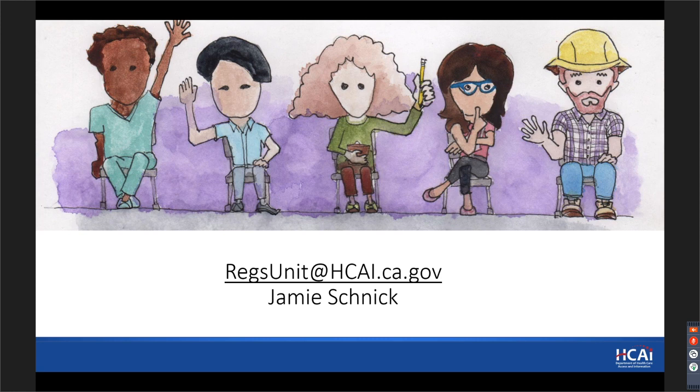So to answer the question, is this required over transformers? The answer is no. To answer the question about whether I am allowed to have sprinkler piping that's 6 feet 6 inches above the equipment, that is code permissible. I would recommend that you have a drip pan so that you don't have the issue of water getting on your electrical equipment, but it's not a code requirement.